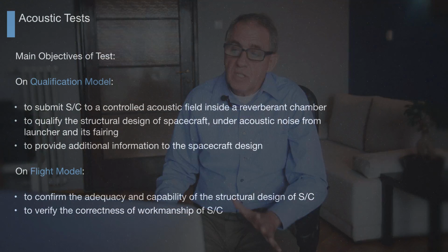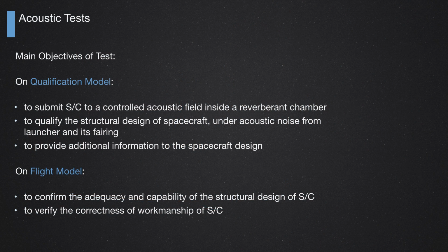But besides that, we also have another vibration on top of the spacecraft. The top part of the rocket, the fairing, while the rocket is hitting the atmosphere at high speed, we have a lot of shock with the atmosphere, and then this shock will produce a lot of acoustic vibration on top of the spacecraft because I still have some gas inside the fairing.